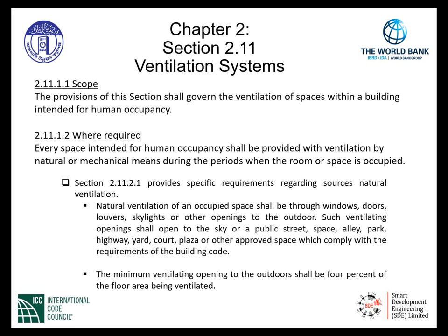The minimum ventilating opening to the outdoors shall be 4% of the floor area being ventilated. So there's a requirement now that once we calculate the floor area, we need a minimum of 4% openable to the outdoors.